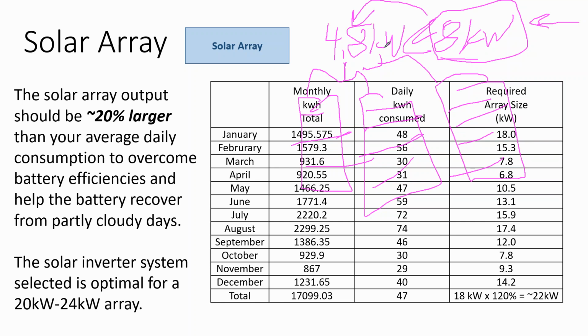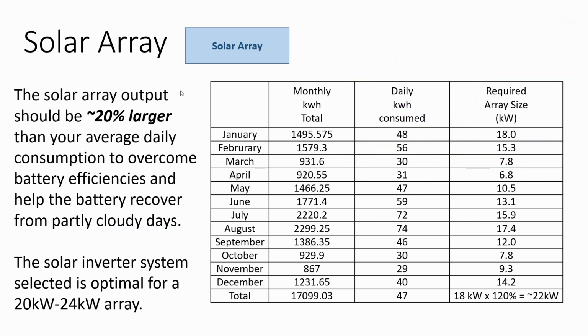And so there's an opportunity for oversizing the DC capacity far beyond what a solar designer might be used to for off-grid design. And for that reason, a charge controller that initially may appear to cost more because it has 3 input circuits instead of 1 or 2 may actually end up costing less, because you don't have to buy a whole bunch of extra material if you want to oversize the DC capacity of the array.